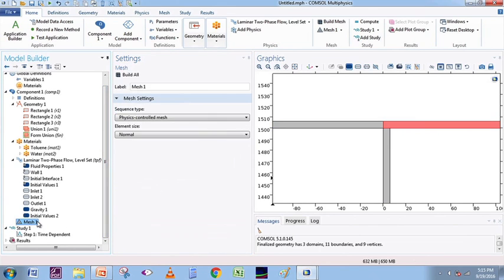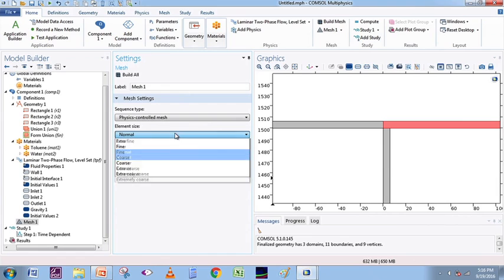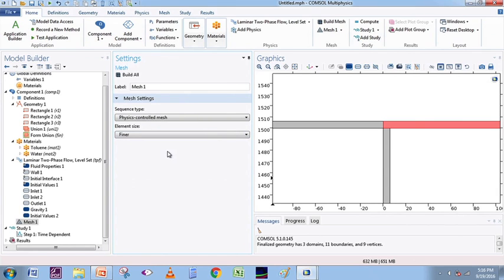Now, the meshing part. As I explained earlier, the selection of mesh size is very important, and it is best to first go for a grid independence test, after which we can be certain about our mesh size. There are 2 different options: physics controlled mesh and user controlled mesh. In user controlled mesh we give our mesh size here, in physics controlled mesh we utilize the multiphysics library for its different meshing criteria, and I select my meshing as finer.